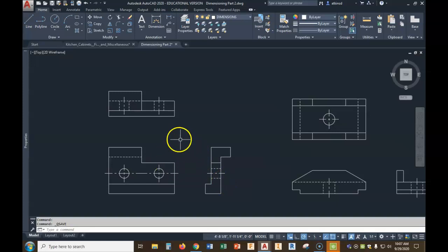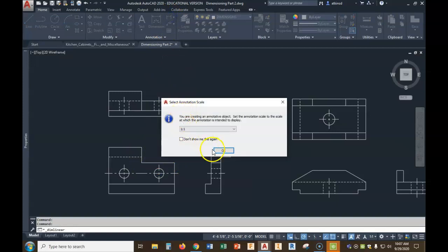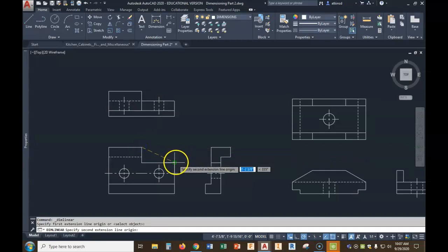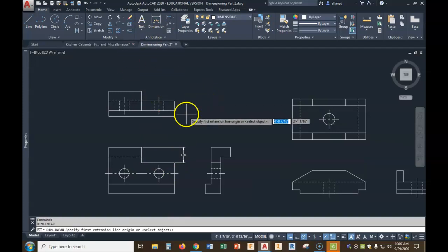So when we get started, here's what we need to look at. Let's see what we've got here. With this feature here, our dimension is fairly straightforward. I'll click Don't Show Me This again so the note doesn't pop back up. We're going to dimension from here to here, and we're going to drag it out here. That gives the height of that dimension, how big the cut is, how far down into the object it comes.